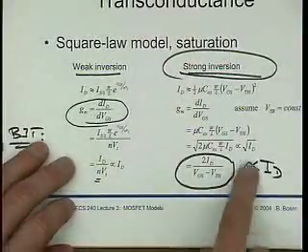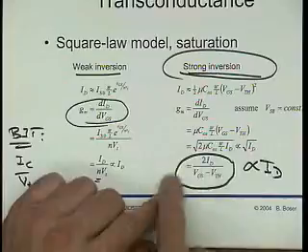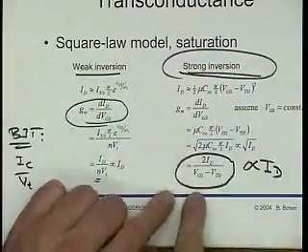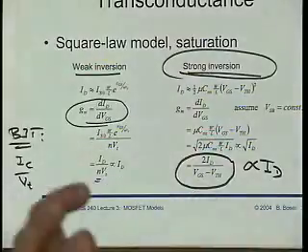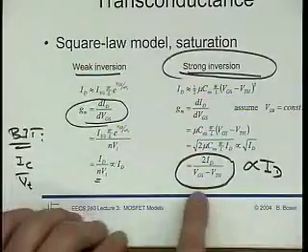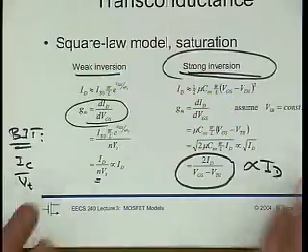I saw this once in an undergraduate circuits course where they used SPICE level 1 models, and SPICE level 1 models exactly use this equation. They had to build the best amplifier under some strange constraints, and it was really possible to make this VGS minus VTH a microvolt and get something out of SPICE that was just phenomenal. Of course, you can never build it. Right?